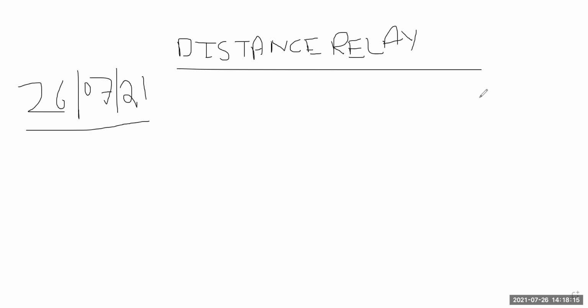We have the frequency relay. This distance relay is also there. For the differential relay, obviously the operating quantity is current. That's why we use CT with that circuit. We use CT in that, right?